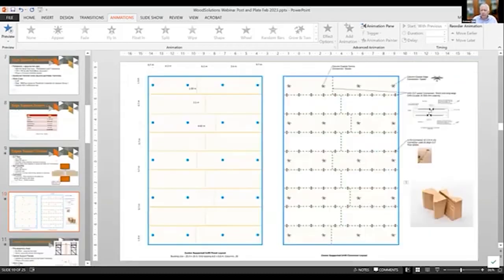In this case, as Perry described, we were putting down a layer of CLT panels down through the column line, and then infilling them. And there's no doubt by doing that process, it reduced the amount of material being used, but the offset of that was the far higher number of connectors being used, and we had a lot more connectors there, which equated to more time. And Perry detailed what those things were.